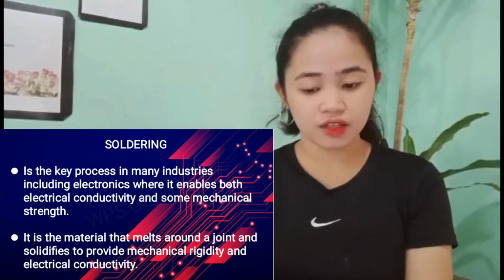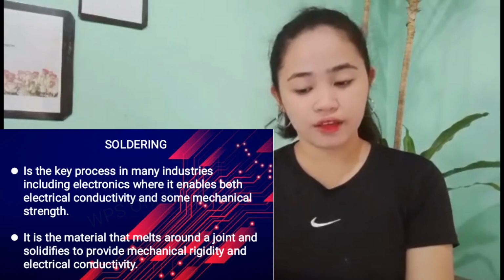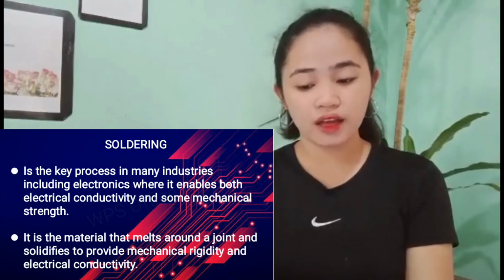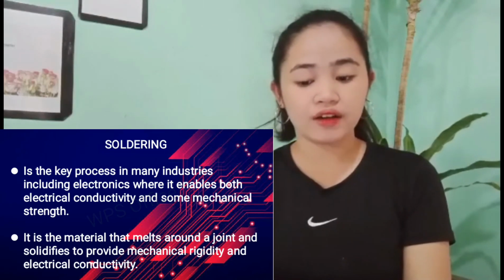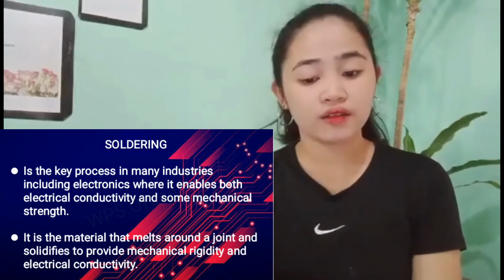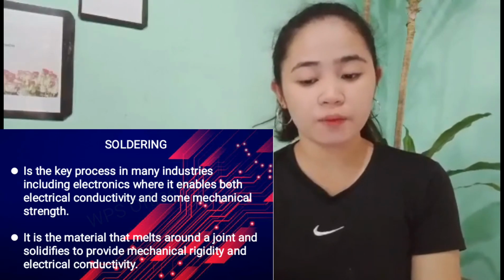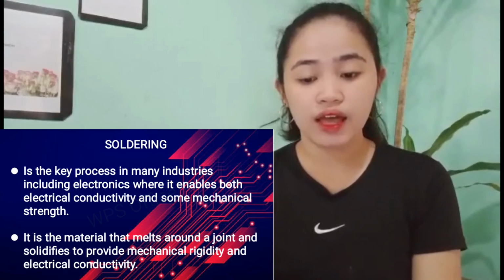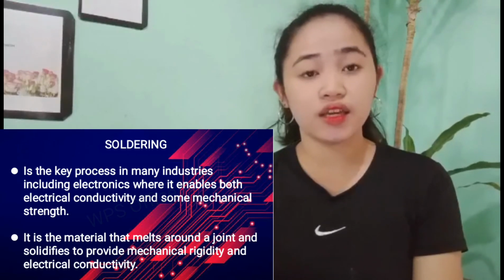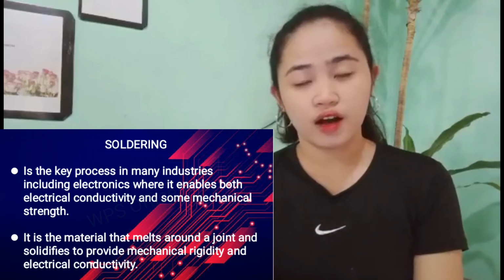Soldering is a process in which two or more metal items are joined together by melting and then flowing a filler metal into a joint, the filler metal having a relatively low melting point. Soldering is used to form a permanent connection between electrical components. The metal to be soldered is heated with a soldering iron, and then solder is melted into the connection.